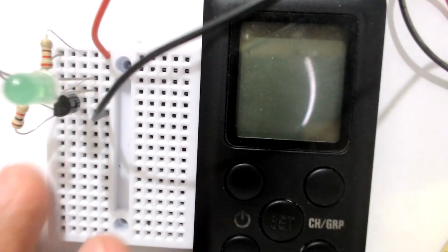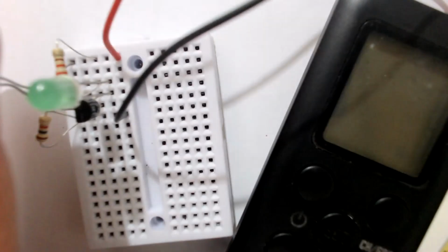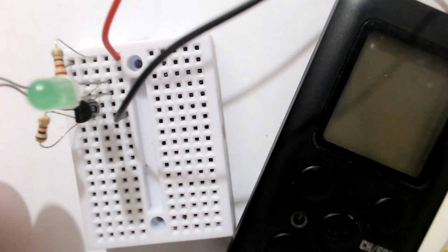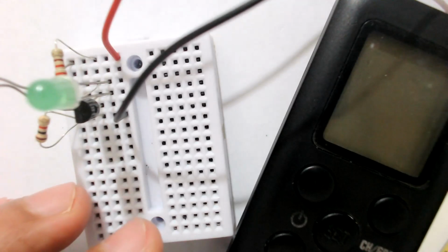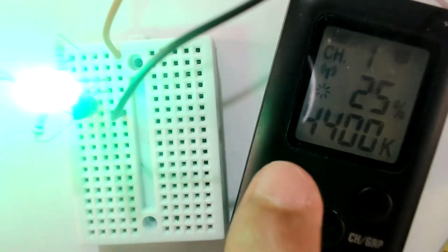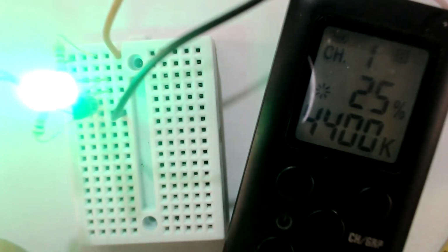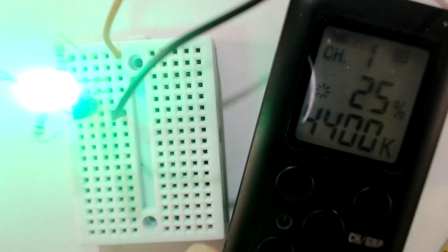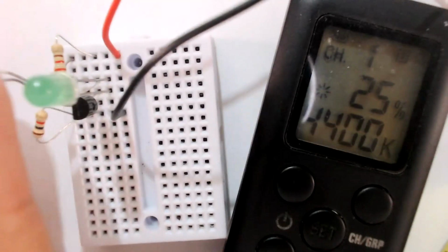In my case also, you can see this is a light detector. The light available is the CFL bulb, and that is not sufficient. When I turn on this studio light, then we have considerable light, and the light detector detects it. That's why some of you asked me, sir, that the detector circuit is not working. It is not a problem of the LDR.